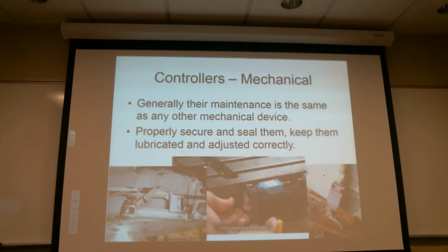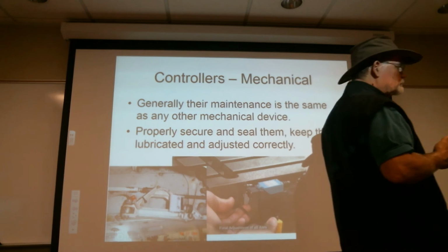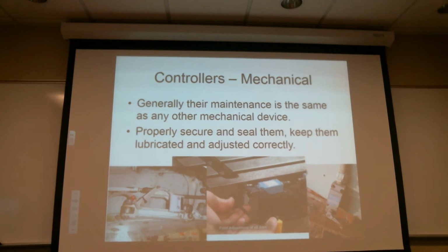Nothing too sophisticated there, but these can be a little bit trial and error too. So, you know, jack the aircraft up, retract, retract. Navion is an example. Navion actually has a switch that says there is no up latch. The switch is actually on the door. As the gear comes up, it hits that switch, turns the motor off, and then the gear are hydraulically held up. If that door gets a little bit loose or the switch gets a little bit misadjusted, every once in a while it'll go, and you keep hearing this strange clunk, right? Well, what needs to happen is the aircraft needs to be jacked up, gear swung, switch adjusted, door tightened up, whatever, to fix that.